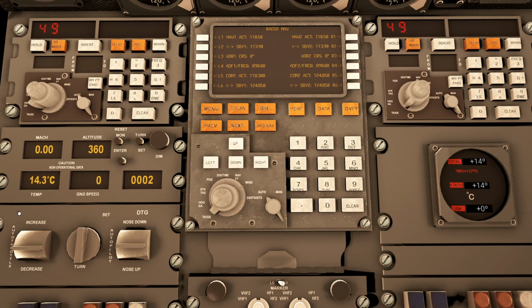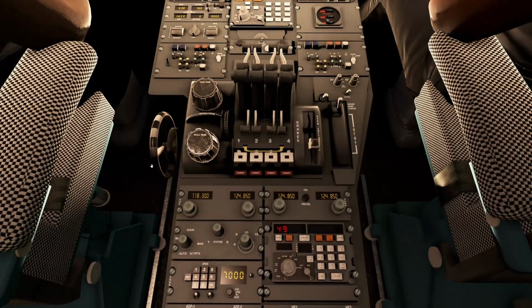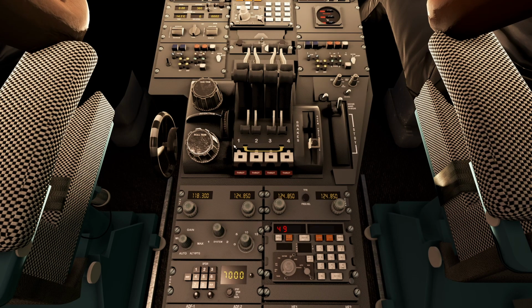Another camera angle that is important I show here. Here you have the control of the afterburners. Do not let them be turned on if you're in auto throttle, or your autopilot is going to use the afterburners if you don't want them to. So you turn them on and then they are available either with autopilot or your manual thrust.